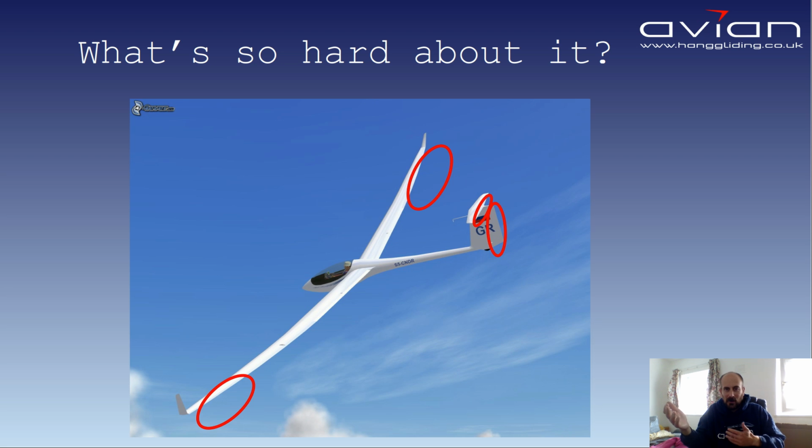If you're going about designing an aircraft like this, although admittedly it's a whole lot more complicated than this, in principle, if you design a wing which is really efficient, and then you put a tail plane on that which gives you enough stability, and then you add a rudder to give you enough yaw stability, and then you put control surfaces on which are sized big enough to give you the required control, then you'll have a pretty good aircraft.